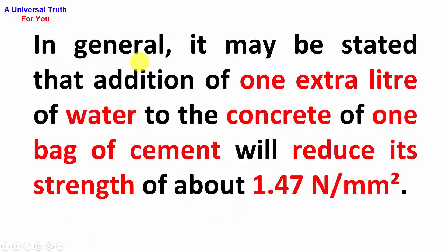In general, it may be stated that addition of 1 extra liter of water to the concrete of 1 bag of cement will reduce its strength by about 1.47 Newton per mm square.